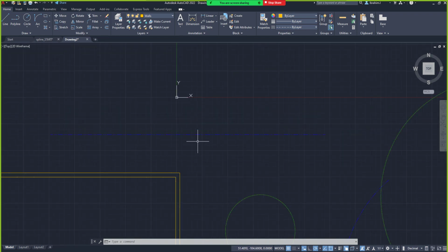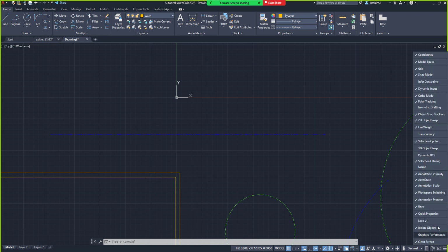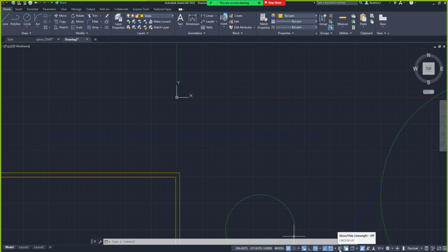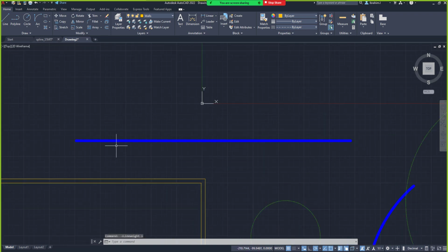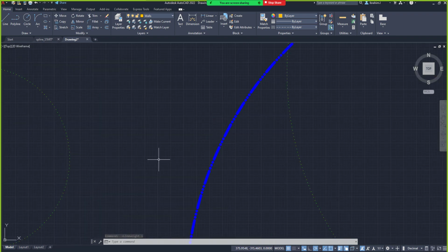The reason why it's not showing is because on your status bar, there's something called line width. It's already here on my own design, but if you can't find yours, you go to that donut icon, the customize, and then you try to locate it here. It is called the line width. Can you see line width here? Mine is checked. Can you see that? The icon for line width is this that we have here. Line width display. Can you see it's currently turned off? When I click on turn on now, can you see that the line width is now applied? Can you see that?